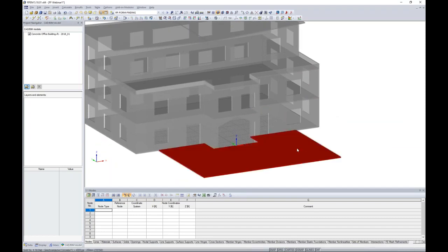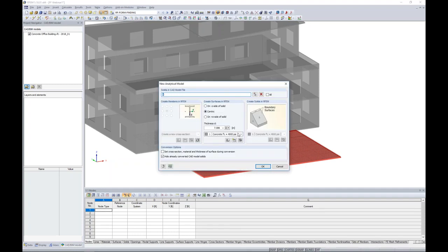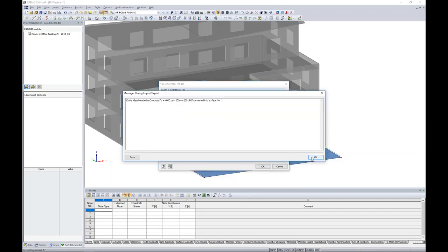So what I can do is take one of these elements, and in particular, we'll start here with our front slab. I can right-click to create a surface. Now, the program generates some arbitrary thickness and selects some material within the model. This really doesn't matter. We're actually going to end up deleting this slab. We're purely using the nodes and lines for geometric purposes to generate our canopy structure. So I can just click OK.